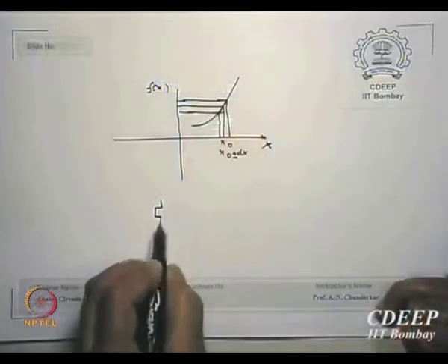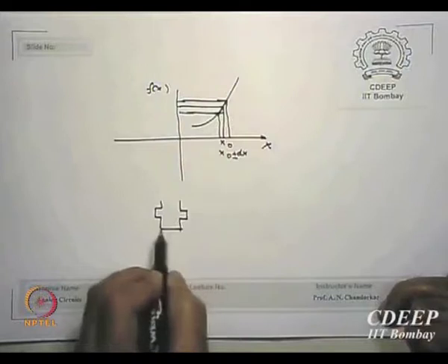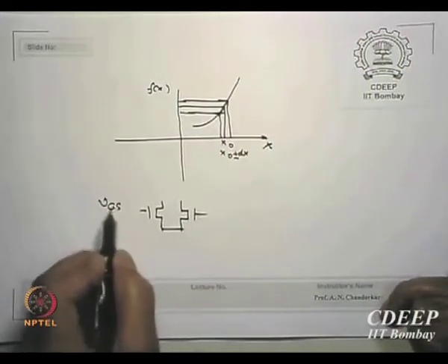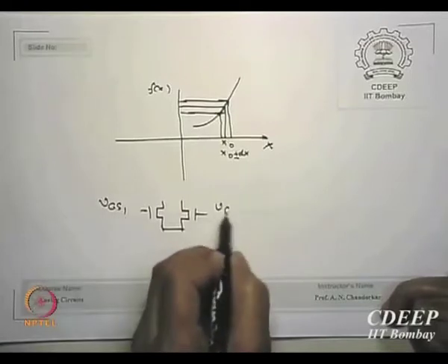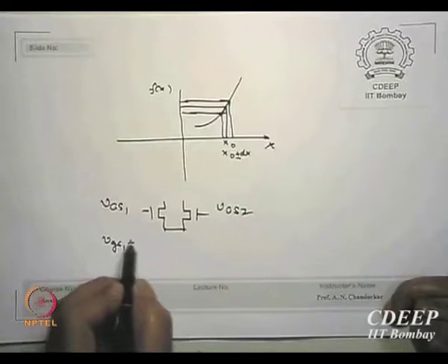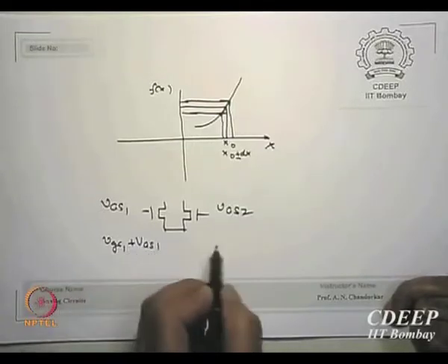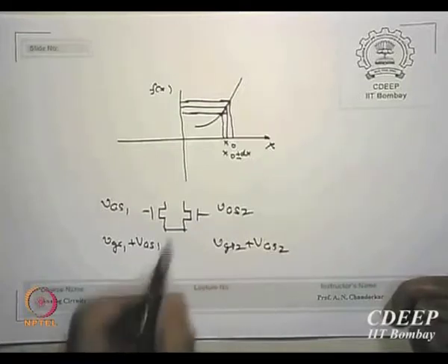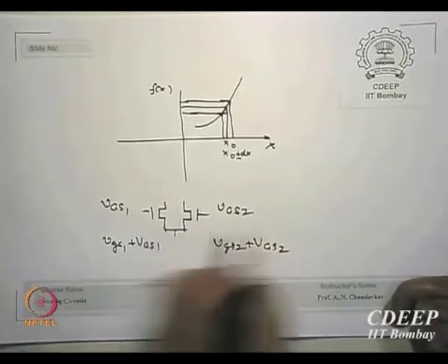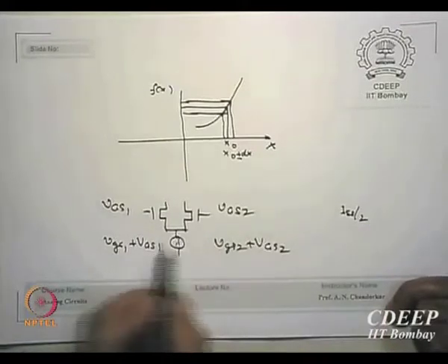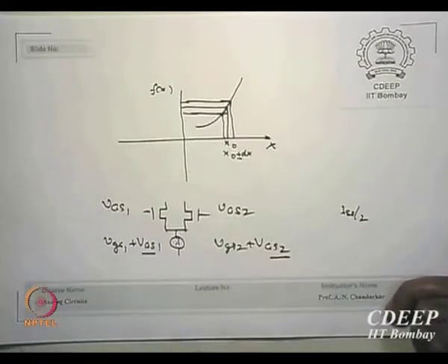In the case of the diffamp, for example, I said if you have small VGS1 and VGS2, it is essentially VGS plus small vgs1, and VGS plus small vgs2, and if the transistor is biased with ISS by 2 on this side, then VGS1 is equal to VGS2.